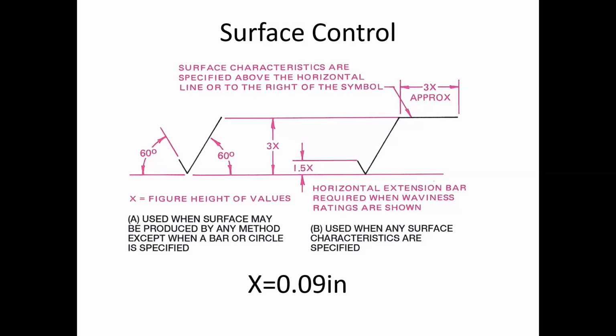Now, that's printed paper size. So if you're working at a scale, either you're using annotative, and all this stuff is printed paper sizes, so you have to account for the scale to get your stuff right. In Inventor, I think the symbol is going to come in much larger than this. So how close are y'all getting your Inventor legs under you? Pretty good. Are you making drawings yet with dimensions? Oh, yeah. Okay, well, this may be the time because Inventor does have a surface texture symbol, and you just pop the numbers in and it pops it right in.